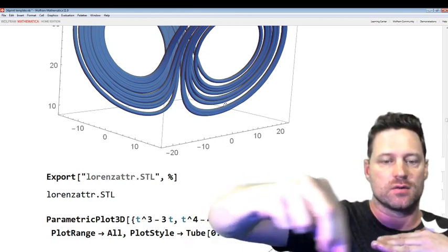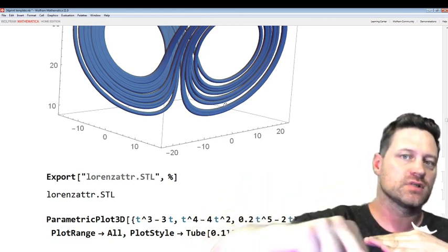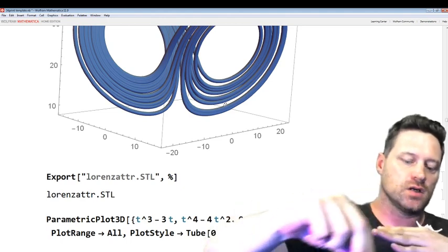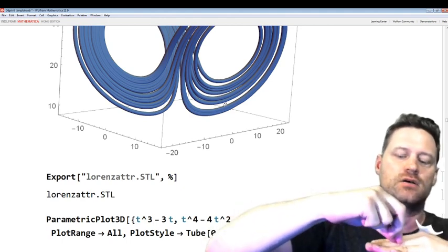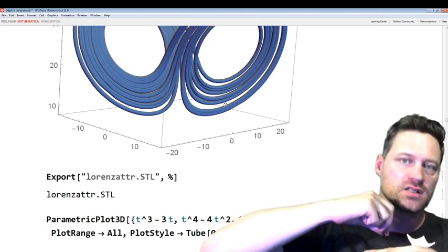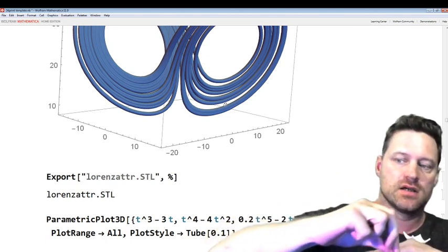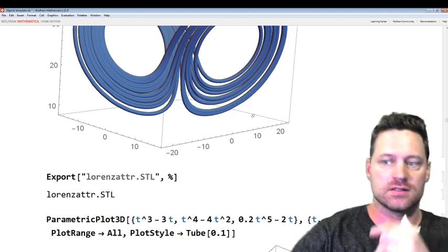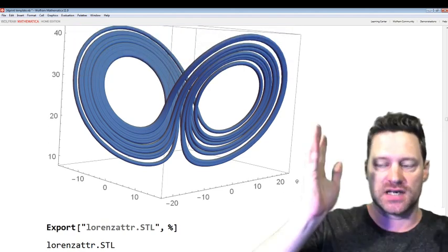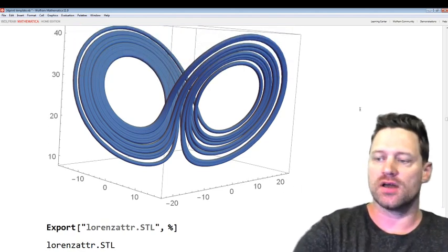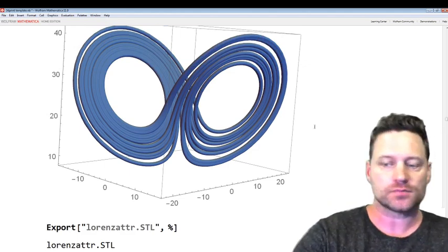If the print nozzle comes along like this, it's got to deposit its print material onto something, not just empty space. So you have to support all of these with some support material. So it's not just the model, you have to build supports when you do this.